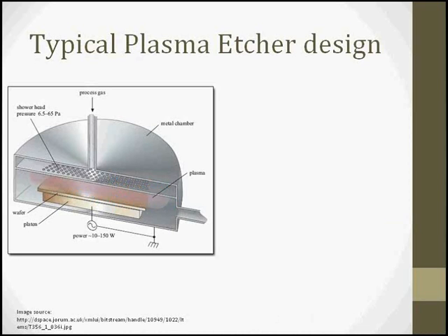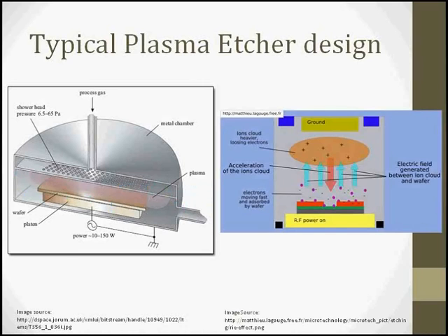And we have a plasma that gets generated within the space between the electrodes. So this RF will power this electrode, the upper electrode and walls will be the grounded electrode, and plasma is generated between them. When we have a plasma generated in the chamber, the highly mobile electrons will end up moving quickly to the walls and charging them negative. The wafer will develop a negative bias, and there will be a plasma sheath formed between the electrodes and the plasma. And in that sheath, it's a dark space with a lack of electrons.